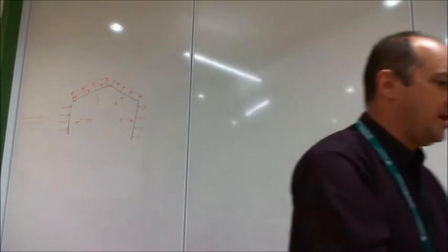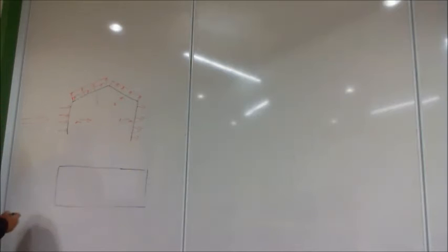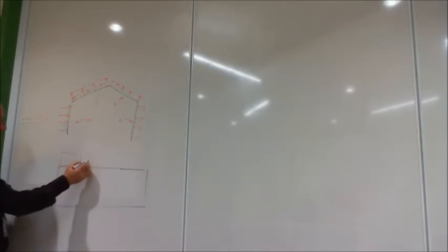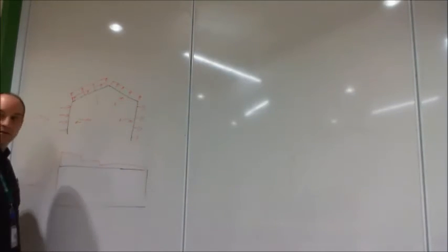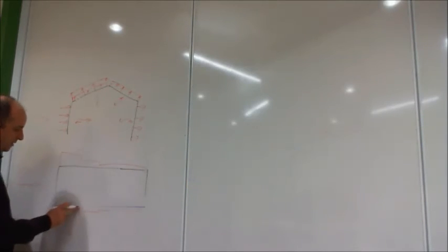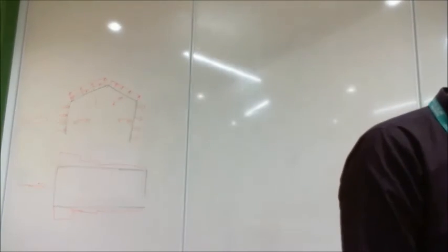All right. That's good. Now let's draw this building in plan. So let's say it's quite a long building, and you've got a wind blowing like this. If you look in the sidewall factors, you have a sidewall force which starts off quite high and then it steps down and then it steps down again. And same on the other side. And where it steps down is proportional to how high the building is.